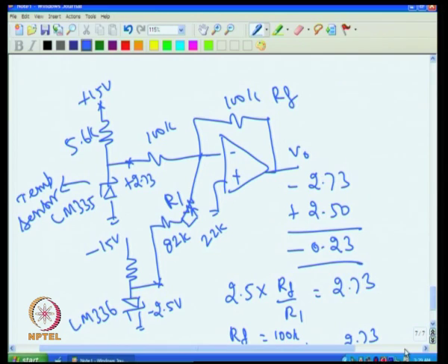So, you can adjust this potentiometer, say I will call this P1, and of course, this resistance is R1 here. So, you have this resistance we call R1, 82 K, and this is P1. So, adjusting P1, we can calibrate this instrument, that is, keep this one at ice and adjust P1 to get 0 volt at this point, that represents 0 degree C.